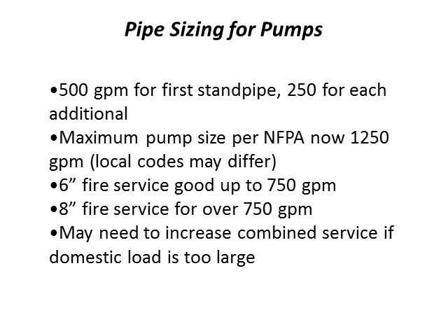Remember, for pipe sizing for pumps, it's 250 GPM for the first standpipe, 250 for each additional standpipe. Maximum pump size per NFPA right now is 1250 GPM. Local codes may vary.